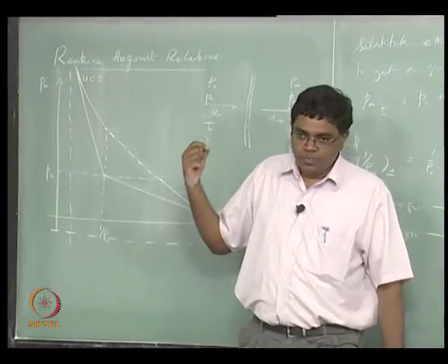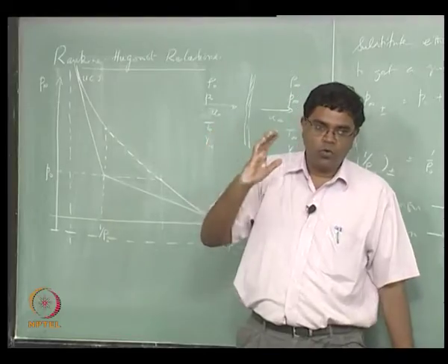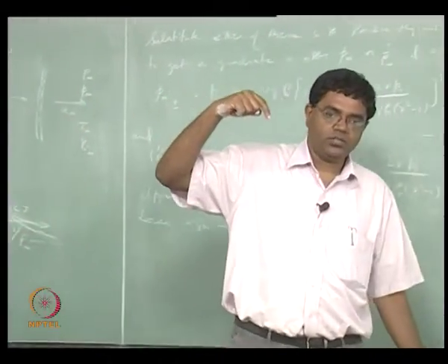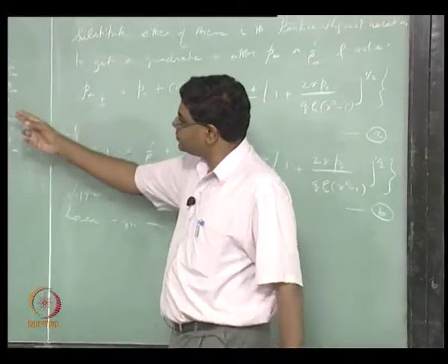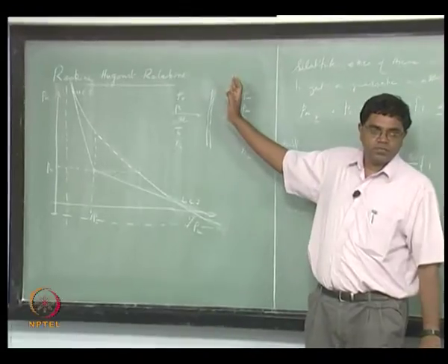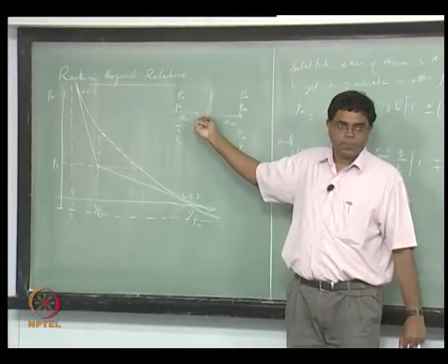Now keep in mind, how fast the wave is going to travel is information that's contained in u naught, okay, because in a wave-fixed coordinate system you are going to have the reactants travel to the wave at that speed,